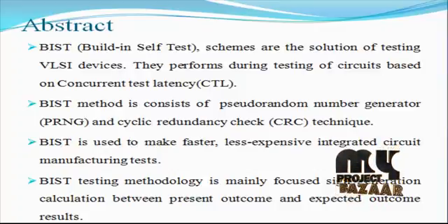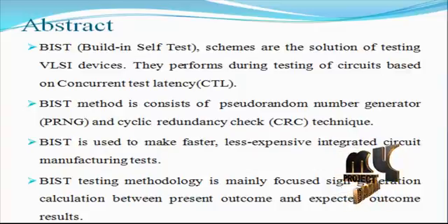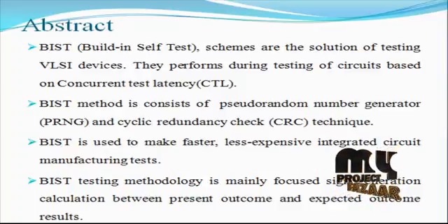It is compared with linear finite state machines, a linear feedback shift register and a ring generator driving an appropriate phase shifter, and it comes with a number of features allowing this device to produce binary sequences with pre-selected toggling activity. We introduce a method to automatically select several controls of the generator, offering easy and precise tuning. The same technique is subsequently employed to deterministically guide the generator towards test sequences with improved fault coverage.